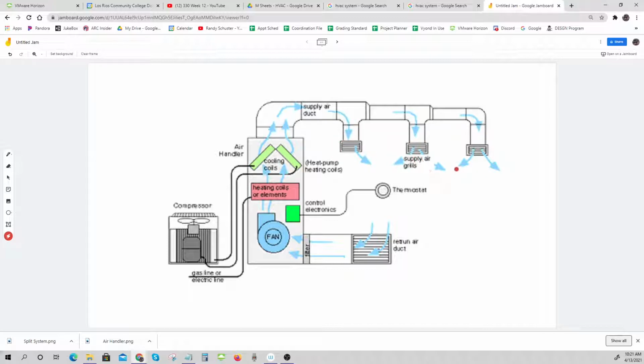Now that's very, very simple sounding. And this is one of the most complex parts of any design that you'll ever see because there's so many factors. There's how much open area is there and how much is flowing through and what the pressure is at each one of these spots and how far apart these are and how high up off the ground they are and what the throw is and even how many turns, how often you need to replace the air in this area.